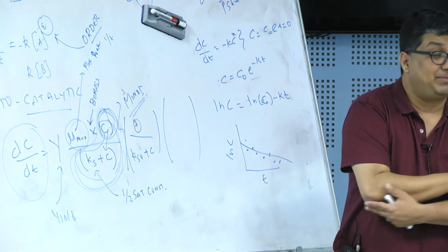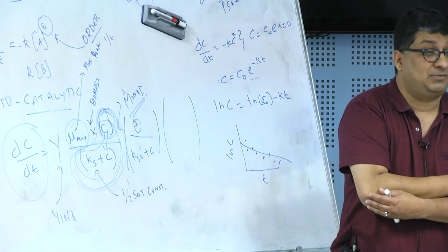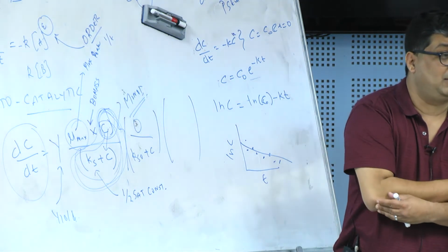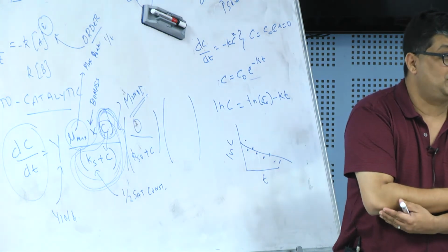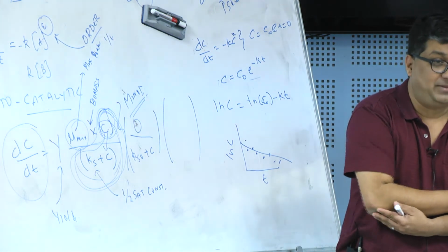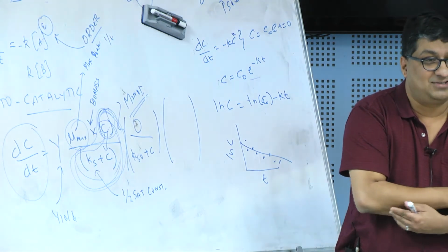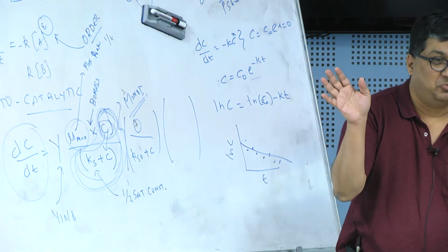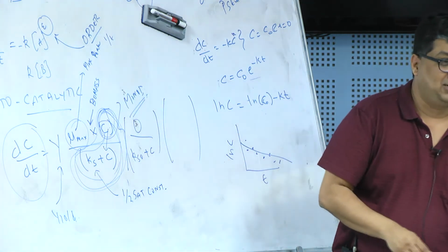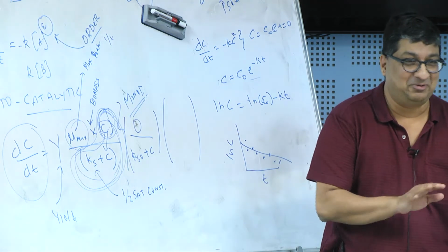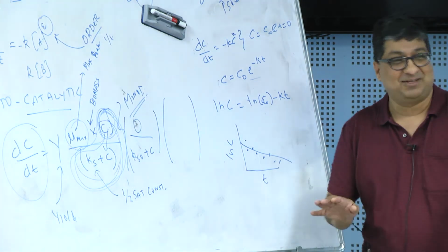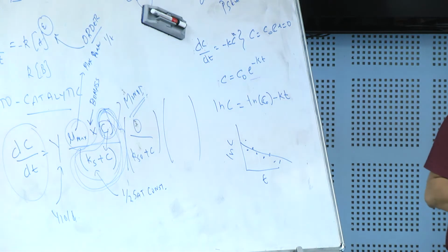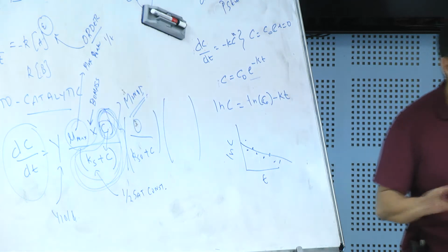The other thing that happens in wastewater, which is why chemical engineers look down on civil engineers sometimes, is because we make approximations and we don't tell them. Okay, we generally assume that the biomass concentration is 1 and get rid of that x. Okay, it's not Monod kinetics at that point. Mr. Monod never said to do that. Okay, some civil engineer decided I can't solve this equation, but if I get rid of x, hey, I can solve this equation. So, but really we shouldn't do that.